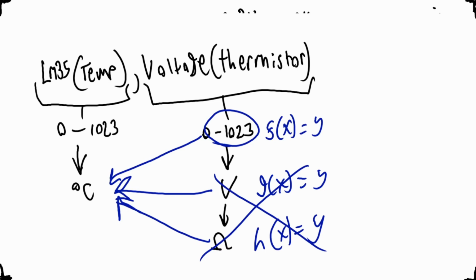The downside of that, by not doing the math for the resistance, is that if you were to then make a completely different circuit with different resistor values, you wouldn't be able to say the thermistor is calibrated anymore. You need to redo the experiment. But in this scenario, because we're just keeping the circuit as is, knowing these values is enough to be able to calibrate the thermistor. You don't need to go out of your way to do all the extra math if you don't want to.